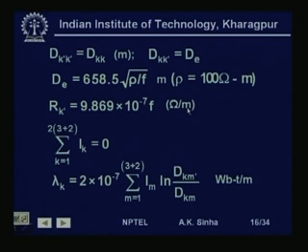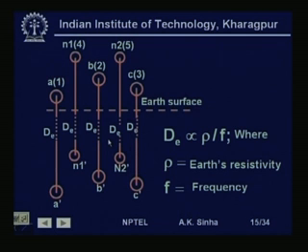So, dE and R_k dash are empirical values found after lots of experimentation. Now, for this system we have 5 conductors here and 5 image conductors below them at a distance dE from the overhead conductors.